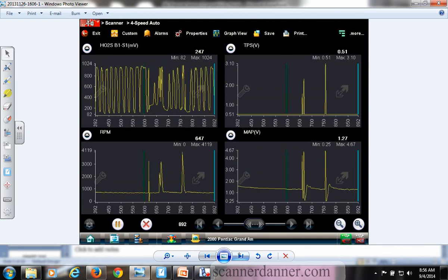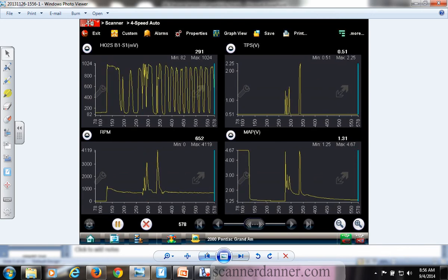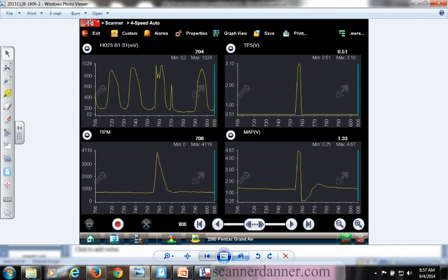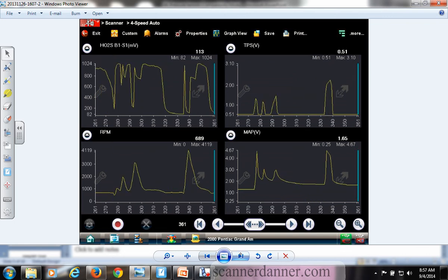All right, what else do we see? These are just some other captures. Same bottom right pictures where you're looking. That's snap throttle with the MAP with the messed up hose. Snap throttle on the MAP with a good signal. This is what we want to see, especially those lower signals. Right, that's a good one there. Those are good ones. That's a bad one.